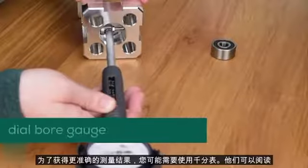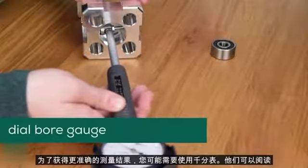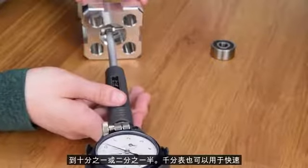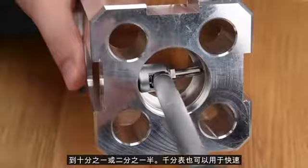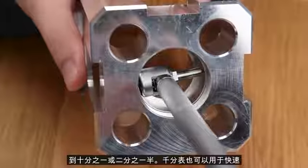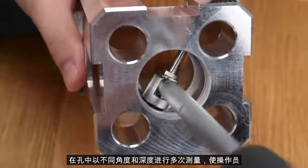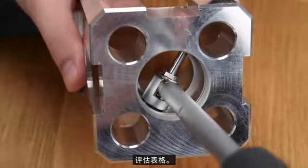For even more accurate measurements, you may need to use a dial bore gauge. They can read out to a single tenth or 2.5 microns. Dial bore gauges can also be used to quickly take several measurements at different angles and depths in a bore, allowing the operator to assess form.